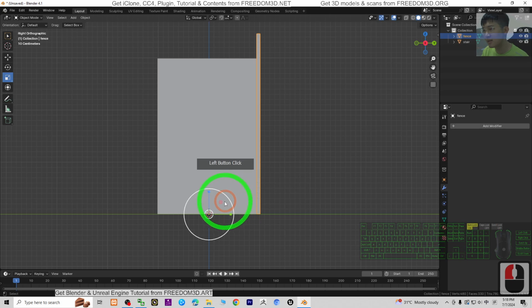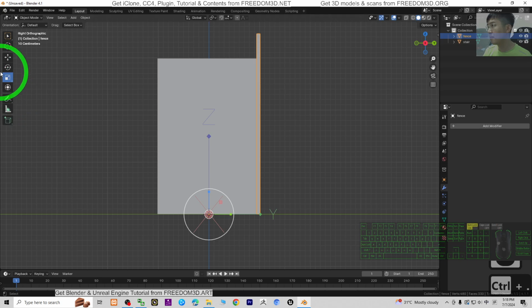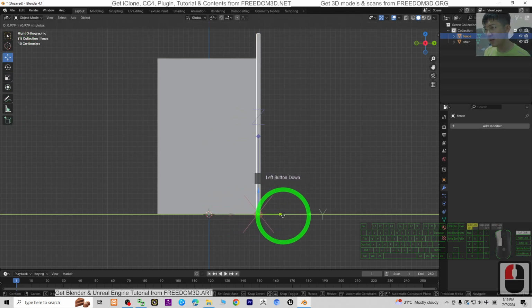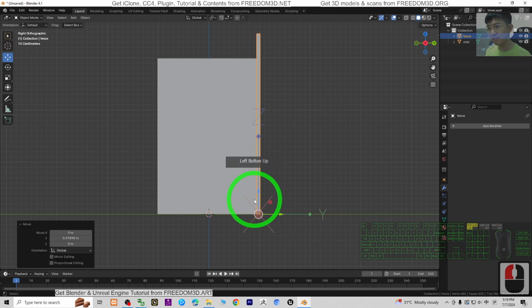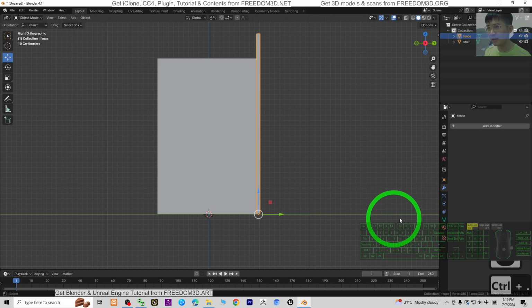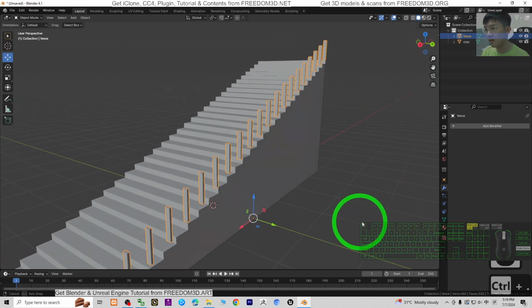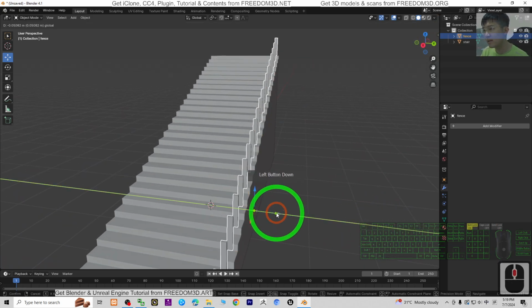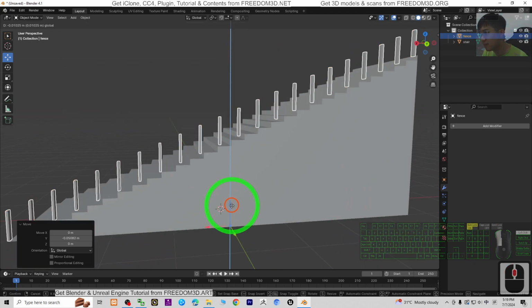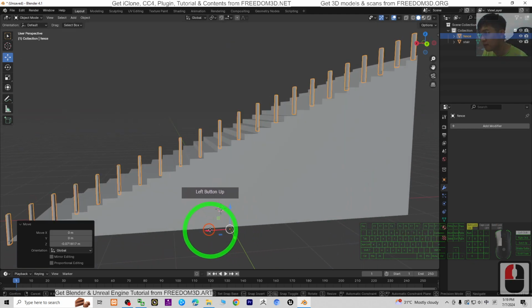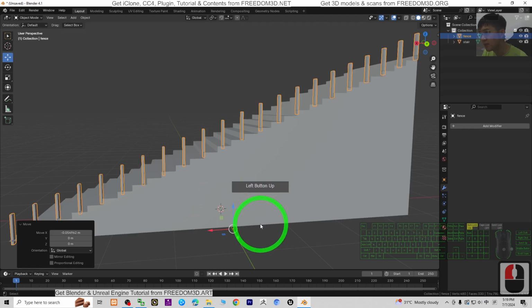You click X, then press Ctrl full stop, click move to make sure the pivot of the pillows are at the center. Then now press Ctrl full stop again. Just have a look. Now you may want to move it, adjust the location. It can be just something like this.